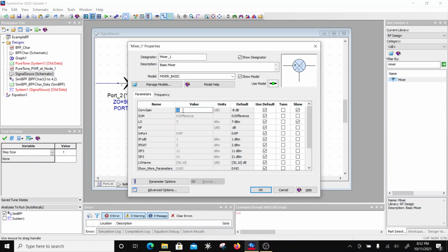So I can say my conversion gain, typically of a Gilbert cell, is around 10 dB or 12 dB gain. Then am I looking at the sideband suppression? So basically if I mix 100 with 3.5, that will be 3.6 and 3.4. You'll get both, right? If you do that.